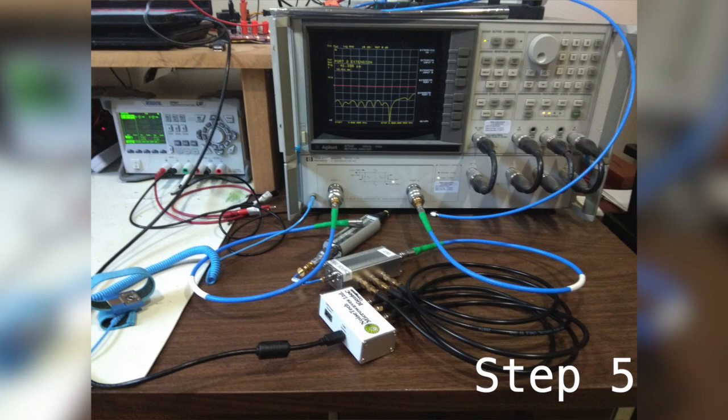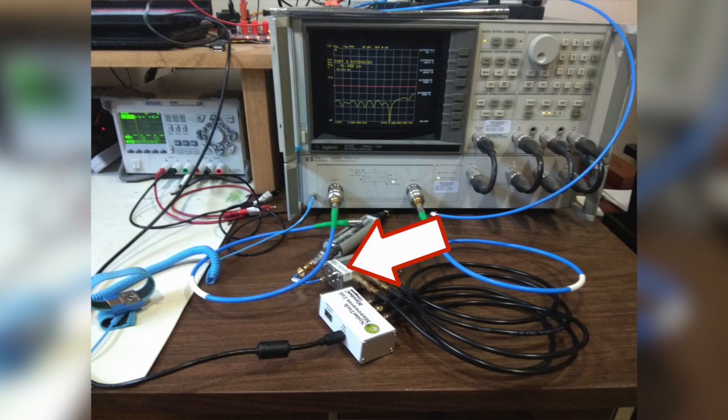So now the noise source is connected to the noise source port of the impedance generator, and the power is turned off. That's step 5. And we're going to measure on port 2 of the VNA the reflection coefficients of the 4 states generated by the impedance generator. So there's state A, B, C, and D. They each have their own separate commands, and we need to measure the reflection coefficients of all of them before we move on.